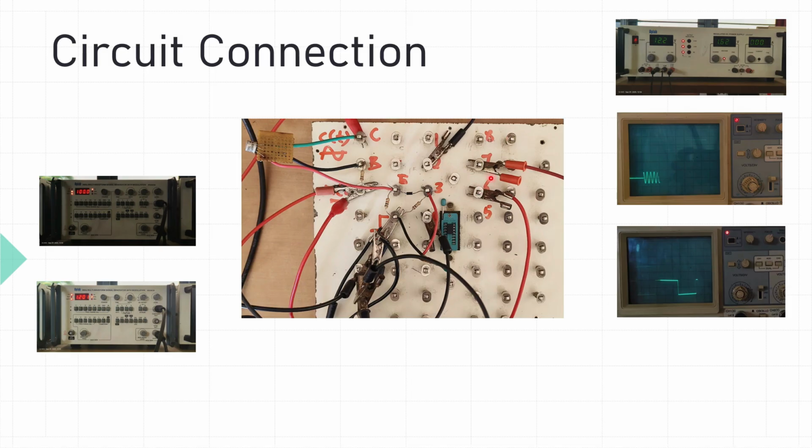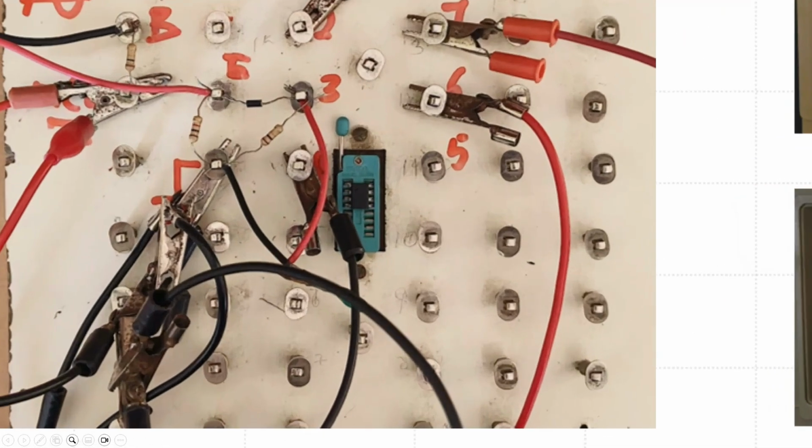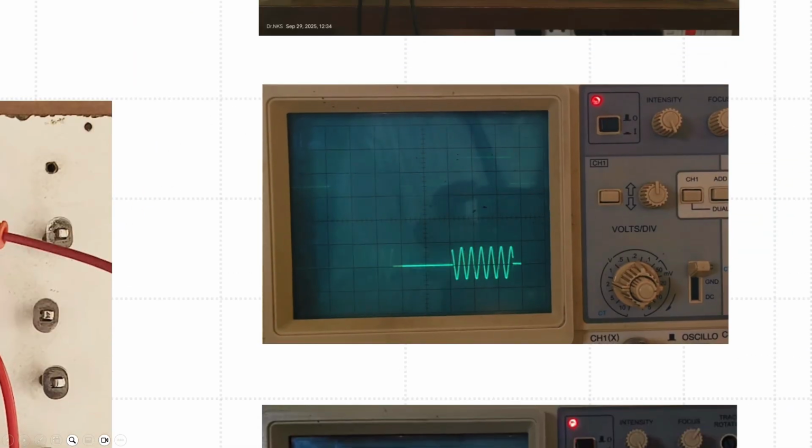When I connect all the cables, that is 3 cables from the power supply to power up the op amp, and 2 signals, that is 1 carrier signal and 1 message signal, and 2 CRO cables that you can see here, the message signal and the output at pin number 6, and turn on, you are able to see the output waveform.